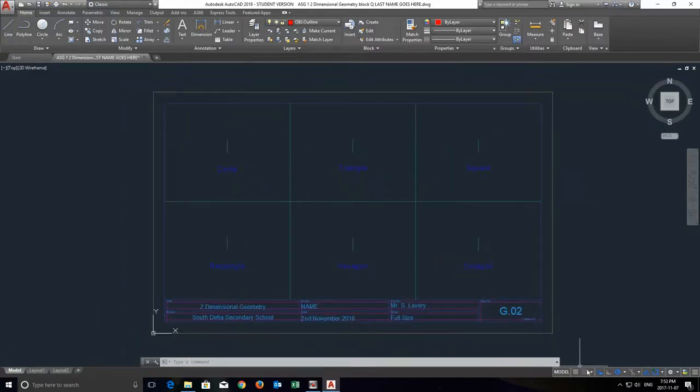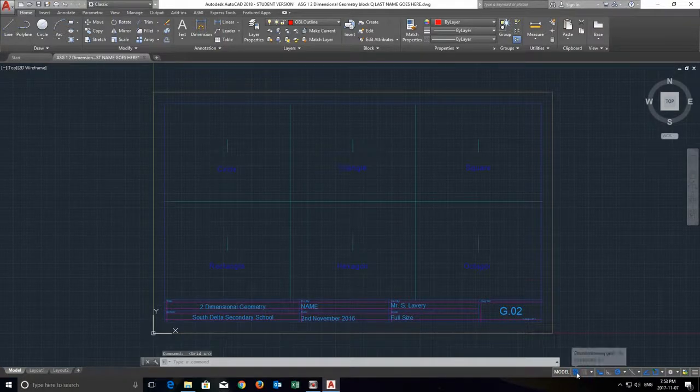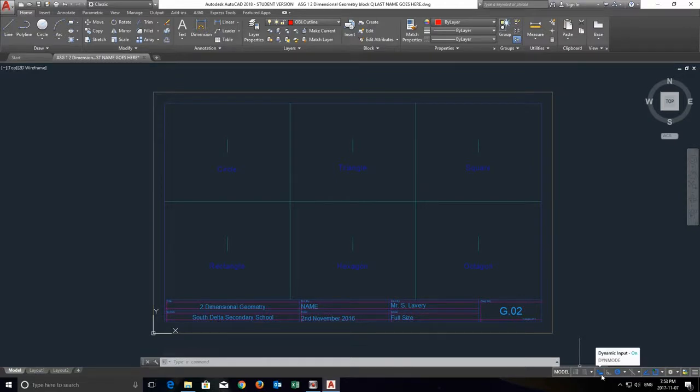Now another thing I need to do is to take a look down here, lower left hand corner. So these are some of the guides and helpers. The idea is if they are colored white, they're off, and you can see right there the drawing grid right now is off. If I click on that, it turns my drawing grid back on, and you'll notice that little icon is blue. So I'm going to click on that again, turn that off. I want the snap mode off. This is dynamic input. You'll see what that does in a bit.